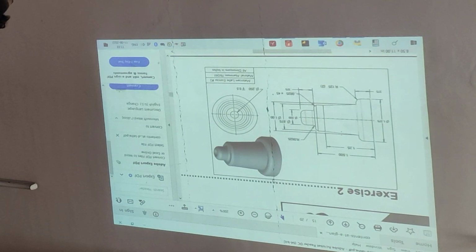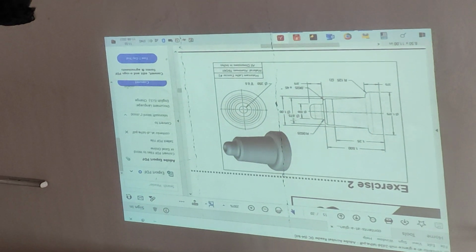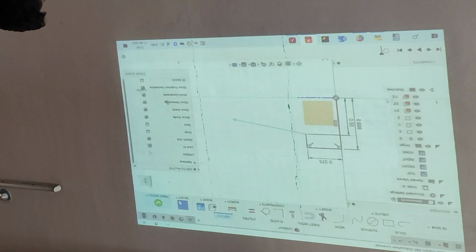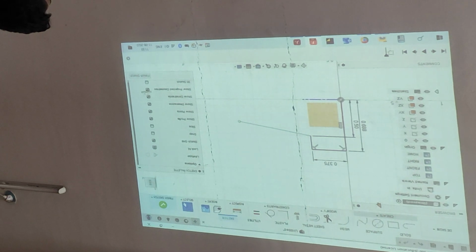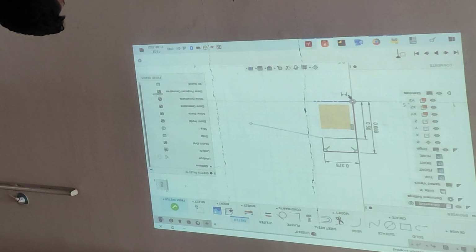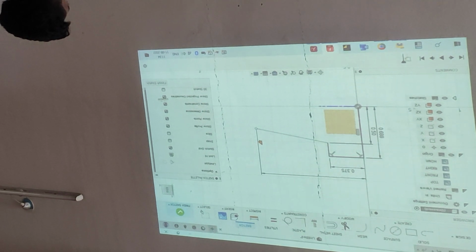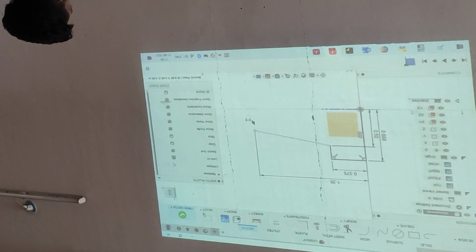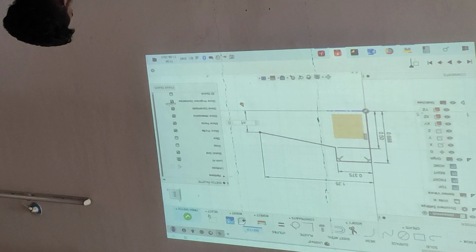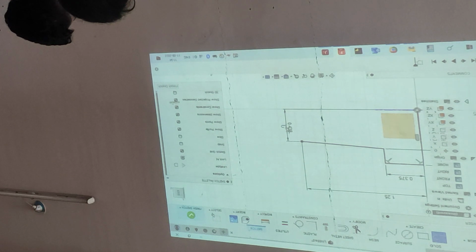I have another dimension here at 1.25. The diameter should be dia 0.875. Okay, so let us do that. First, apply the horizontal dimension. I can make use of the shortcut D and start from this origin to here. This length is 1.25, and the diameter from here to here is 0.875 divided by, that is the diameter. Now there is a horizontal line.